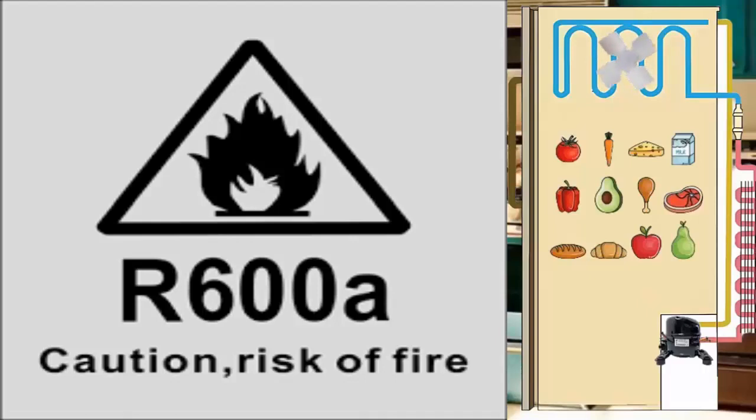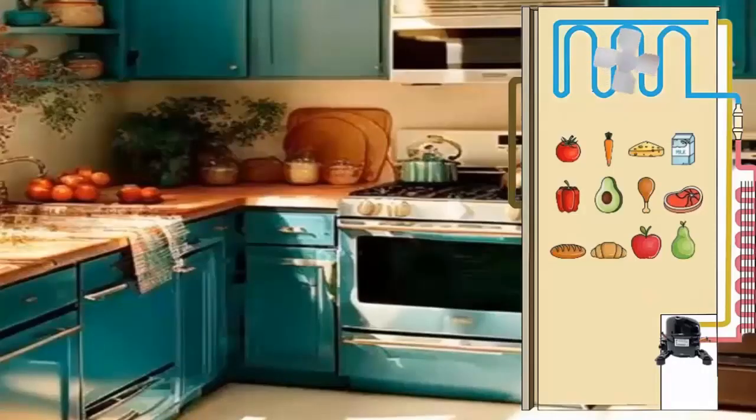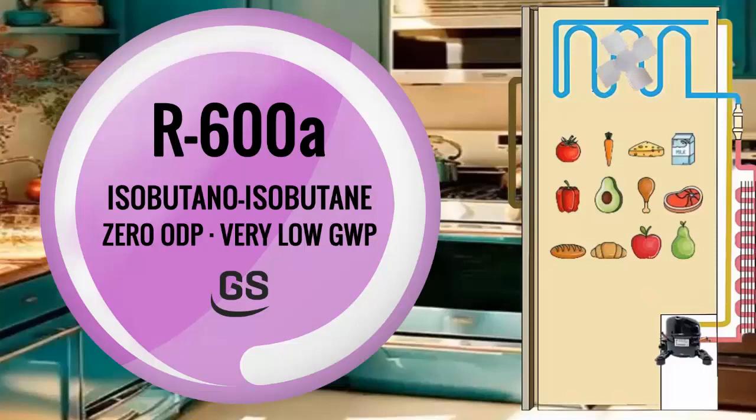The main drawback of R600A is its classification as a flammable refrigerant. However, since domestic refrigeration equipment does not have such high refrigeration capacities, and R600A has a significant cooling capacity, domestic appliances require very little R600A refrigerant, significantly reducing the risk.